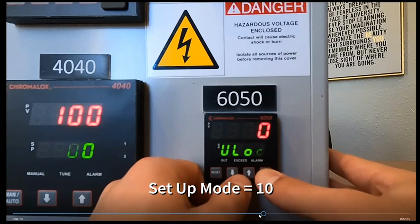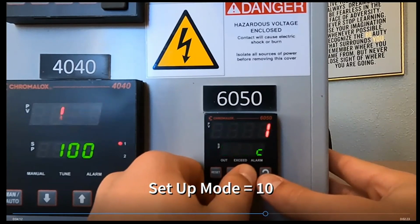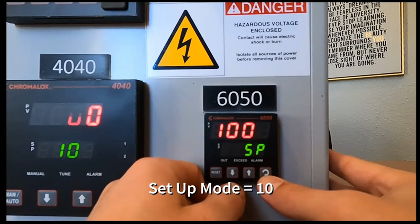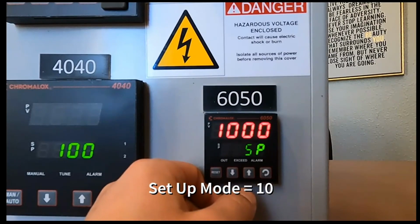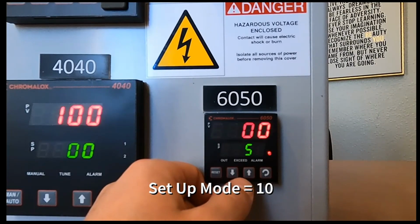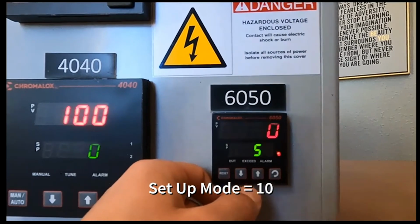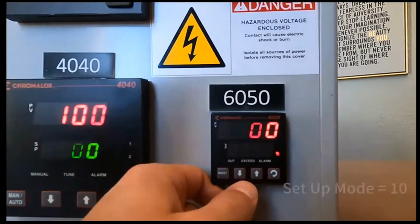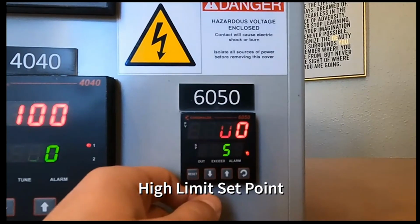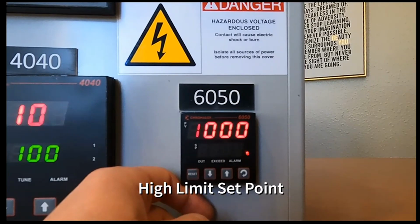Okay, so from here, going to setup mode, same thing as the 40 series, the unlock code is 10. Here is the actual set point of the controller itself. Like I said, it's going to automatically match what we put for that scale range upper limit, which was 1,000. For the purposes of this training, we wanted to drop down this set point just so that we could manufacture an exceed condition.